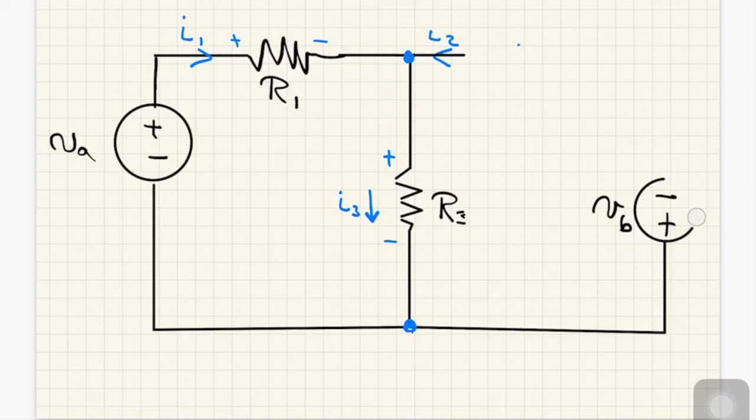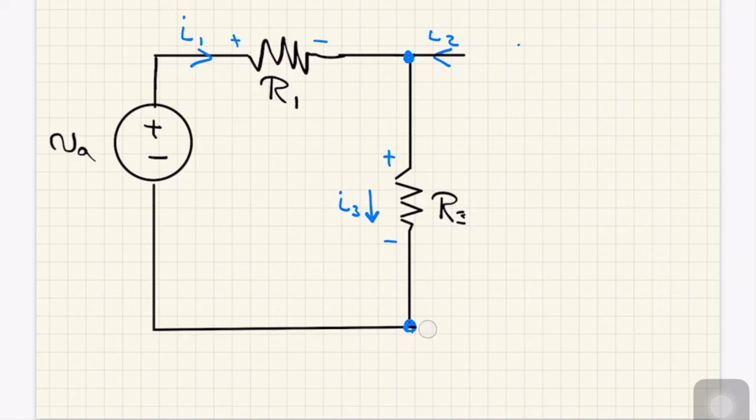So now I can literally erase that entire branch and simplify my circuit quite dramatically. I can get back to a really simple little circuit here in which there is no I2 current. There are only two currents there. So we have a current I1 and I3, and I1 is actually equal to I3. There's only really one current.